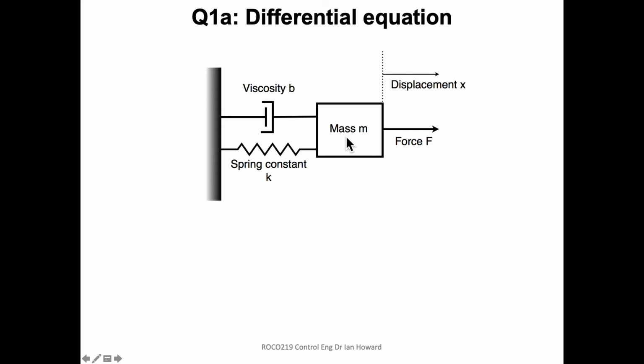The inertial mass itself is going to try to resist being pulled, so there's going to be a component resisting due to the inertial mass. There'll be a component in parallel resisting due to the fact that the viscous damper is also trying to resist being pulled forward, and this time it's going to be resisting by B multiplied by the velocity it's moving at. The spring constant K of the spring is going to result in a force resisting which is proportional to K times the displacement.